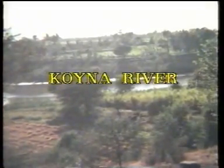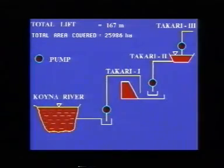The water from Koyna river is planned to be diverted through a system of weir and approach channel to forebay of Takari Stage 1 and then lifted by pumping 63 meter using vertical turbine pumps into the forebay of Takari Stage 2.